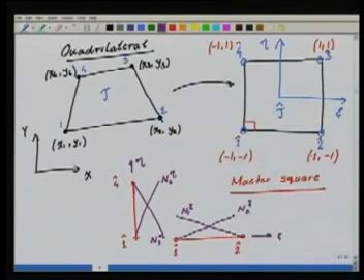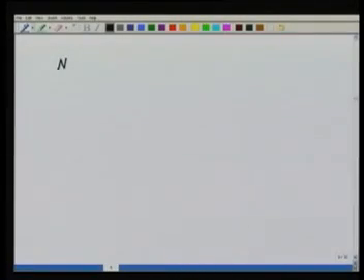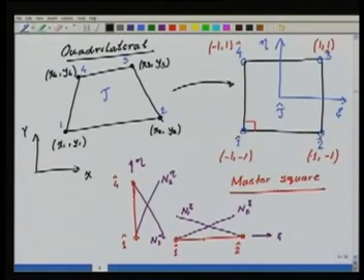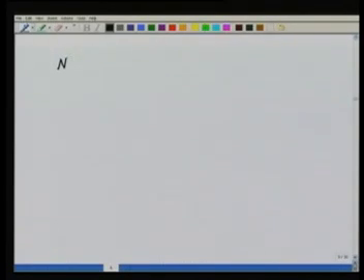Okay. So this way now I can define these 1D shape functions on the psi edge and the eta edge. And in terms of the products of these 1D shape functions, now I can define the shape function for the master element. So now if I have to define the bilinear or the linear approximation, because it's a tensor product, it's called a bi-p approximation. Okay, which means it's p in one direction and p in the other direction. So it's a product of these two p's. So when p is equal to 1, it's called a bilinear approximation.